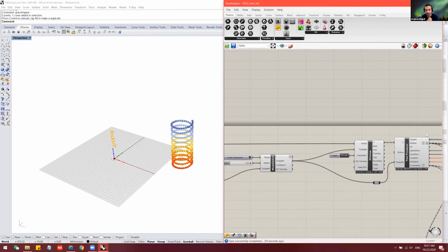But for now, I was pretty sure because you could see that the problem was rising at a certain level. Below that point, I think below target 179, everything was fishy, like the robot couldn't reach them. You can easily say that this is a problem with reachability or reconfiguration. So you just move your targets up, problem solved.